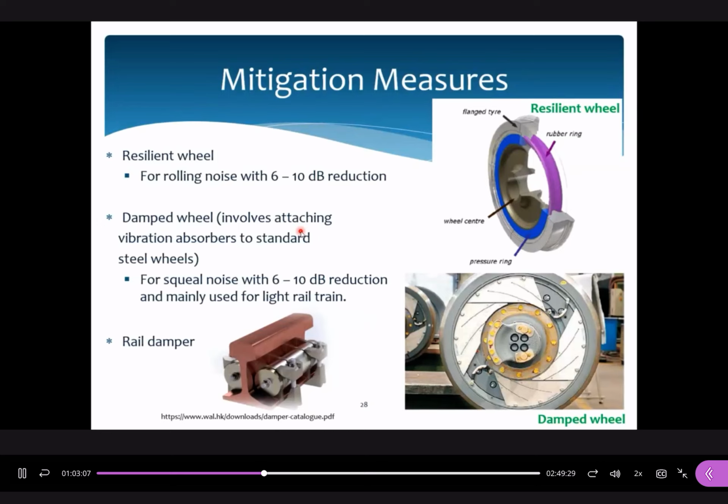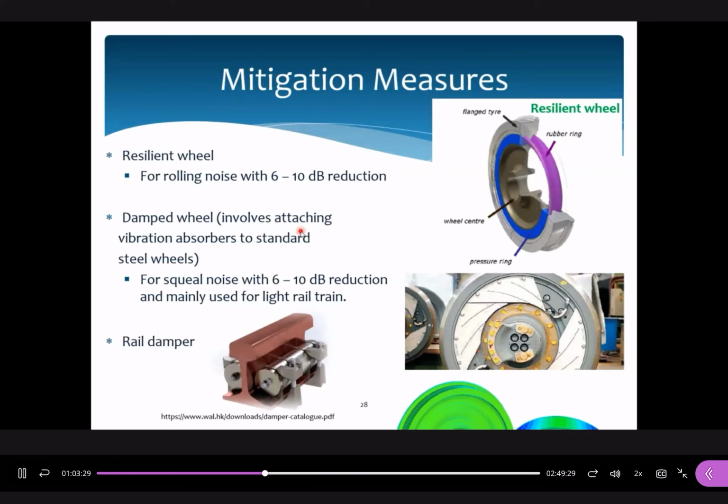It means that under the wind effects, when the building is moving in this direction, the damper could move in the opposite direction to resist the rotations and vibrations of the building. This is what we call a passive tuned mass damper, and we apply this simple principle to the wheel damper here.